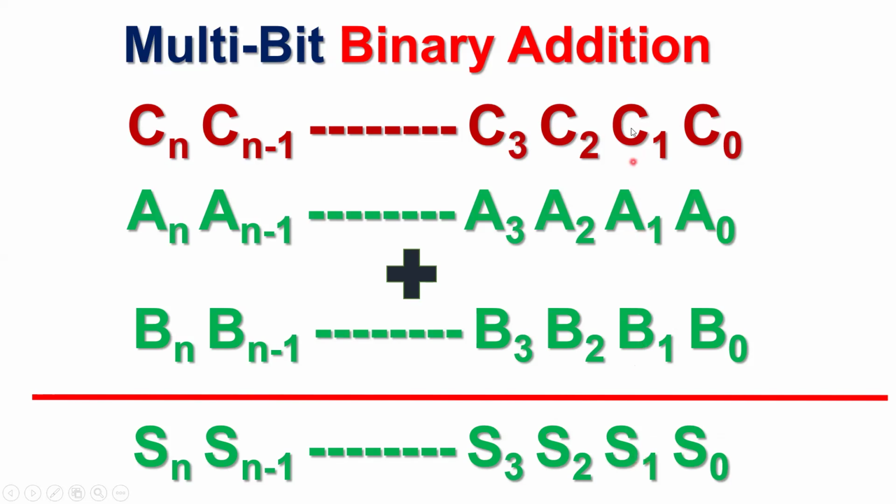If this addition right over here generates a carry, that is represented by C2, that gets added with A2 and B2, finally giving you a 3 bits addition represented by S2. Again, if this addition at this stage generates a carry, that comes here as C3, that gets added with A3 and B3, gives you a final sum called S3. So this process one by one continues.